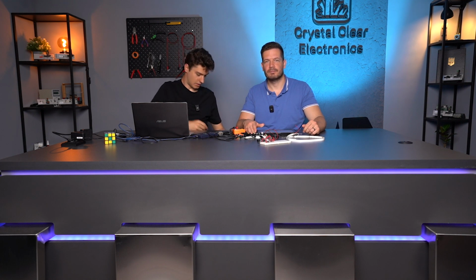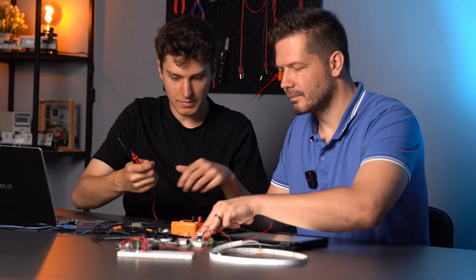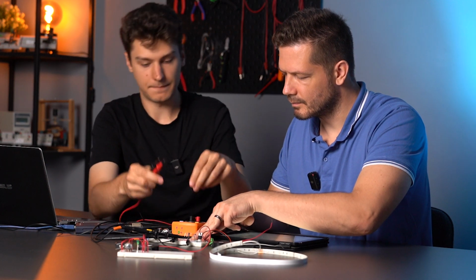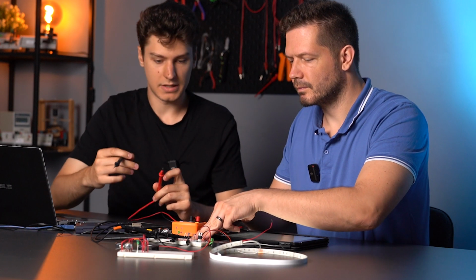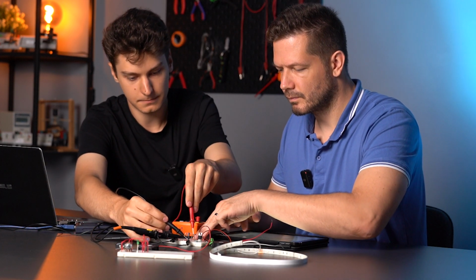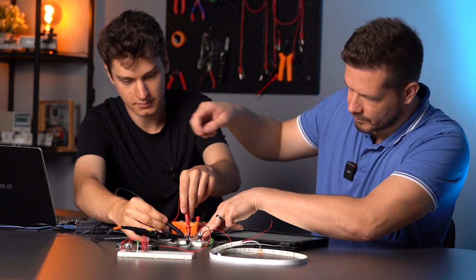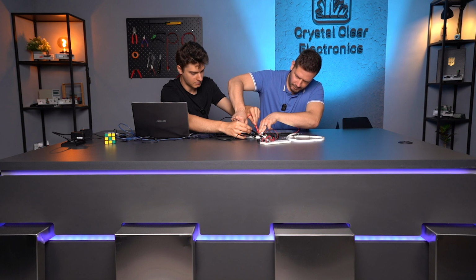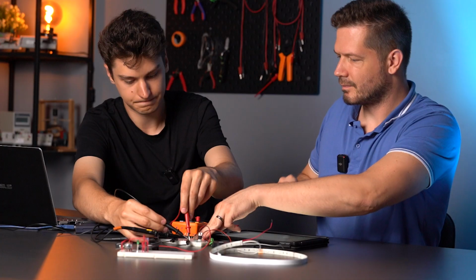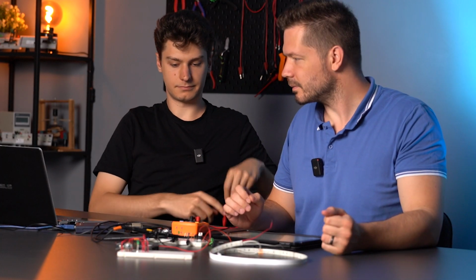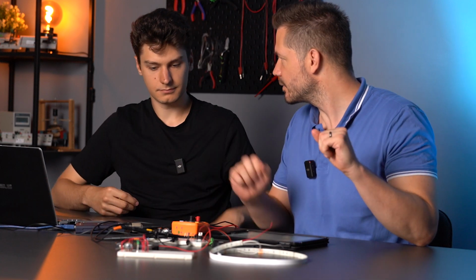Finally, it's time to bring out the multimeter and get some experience with it. I will take it out now. I switch it on in voltage measurement mode, paying attention to the measurement limits. I set this to 20 volts, so there shouldn't be a problem. And then I measure the capacitor's voltage. Meanwhile, please adjust the potentiometer to see how the voltage changes. And I can see that as we change the potentiometer, the voltage magnitude changes here on my instrument. Yes, but in reality, we have a relatively flat signal on the capacitor.